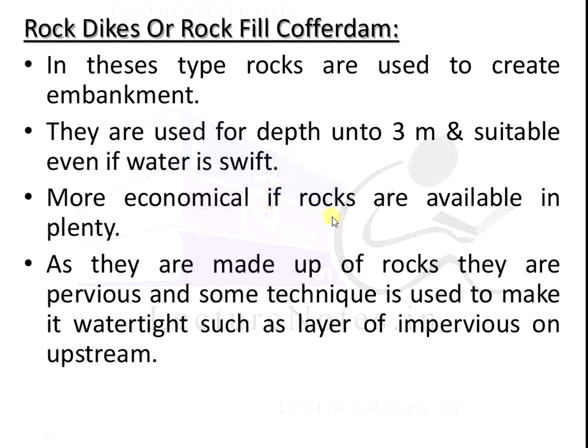It is more economical if rocks are available in plenty near the site. Otherwise, it is very costly. As they are made up of rocks, they are pervious, and some techniques are used to make them watertight, such as a layer of impervious material on the upstream side.